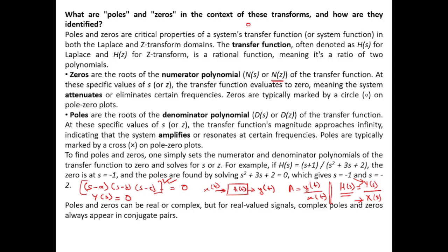Now when that happens, our poles are present on a particular frequency. We discussed this Laplace transform. What is the frequency axis? j omega. Sigma, omega: frequency is present on the y-axis. So if we place a pole on a particular frequency, what will happen? At that particular frequency, it will take the amplitude value to infinity. And when it becomes infinity, that means our system becomes unstable at that particular frequency, and that squealing effect is due to this phenomenon because at a particular point the pole has been placed.